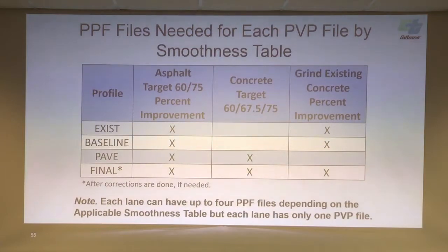We have the profile after they did the corrective grinding, which they comply with, but not the amount of effort, the grinding they did to meet the spec. Since we don't have the profile after they finished paving, we couldn't compare the percent improvement. I was hoping this new spec would require the contractor to submit the pavement profile after they finish the paving.